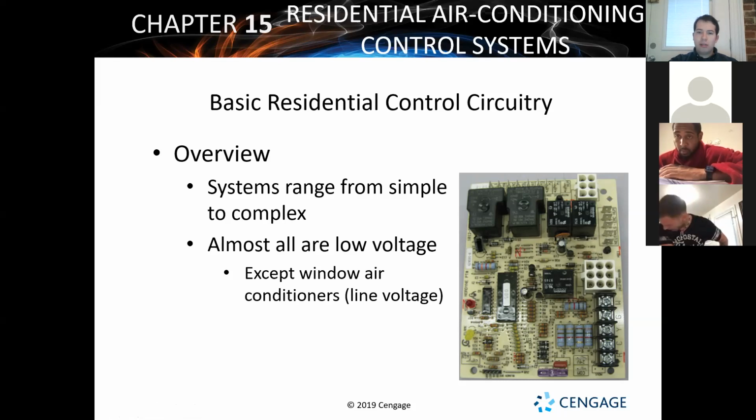And then it's going to go through that board, all that 24 volt signal, everything like that. It'll come into here, it'll go through a couple of safety switches, and then eventually it'll go through a relay. And when that relay closes, there are different kinds, the manual relays, but if you look at this board, you can see these black squares all over it. Those are relays. Those are built into the board. So this might not even have its own independent relay for the fan motor.